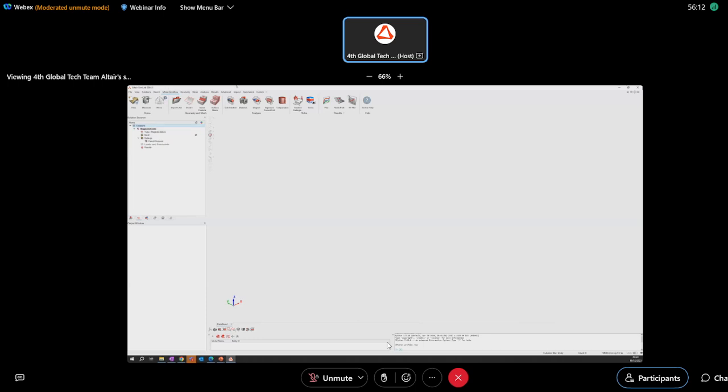So first thing is to create the sketch. How to do it: from the sketch ribbon, you can click on new sketch, then select the yellow plane, and the view will change to the XY plane. You also have the view panel here if you are interested in it. So first thing, we need to create the wire.